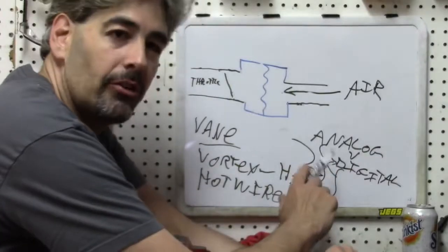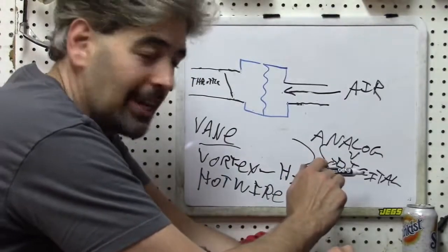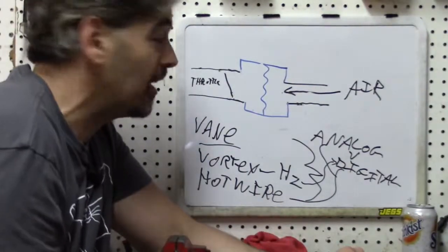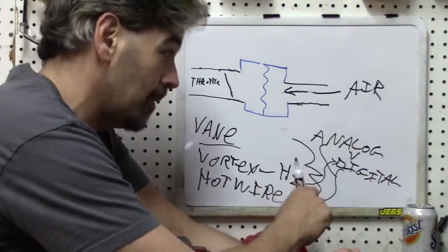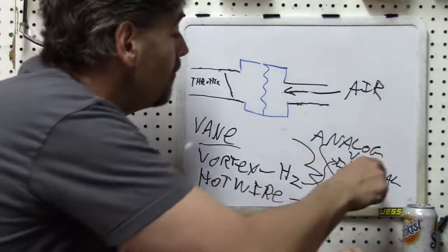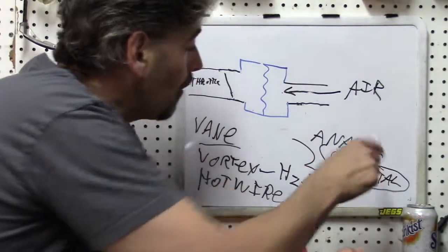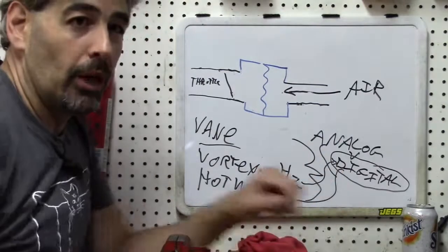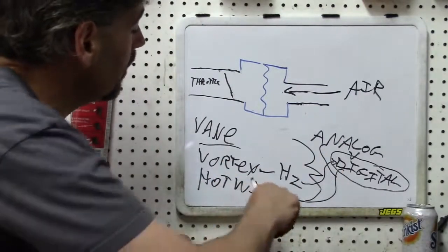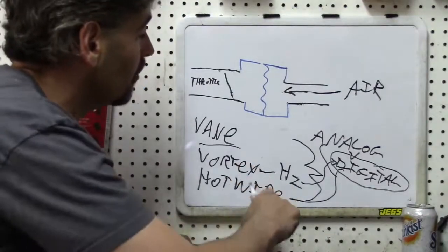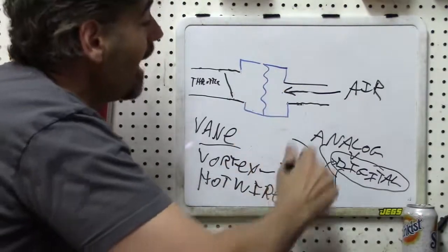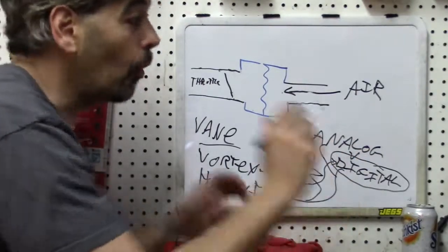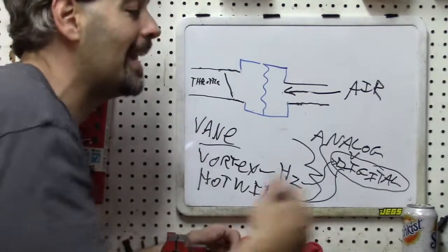We are now going to have to understand the difference between an analog and digital signal, because the testing methods, especially for a do-it-yourselfer without fancy equipment, is going to be extremely different and actually very limiting. In fact, on a digital signal, without the proper equipment, you actually will not be able to do diagnosis on a MAF sensor, and we will understand why in just a little bit. But first, let's talk about the theory of operation of the MAF sensor, because that is going to be equivalent, and then we'll discuss the different outputs that you will be dealing with when you try to make a diagnosis or an interpretation of data from one in a diagnosis.